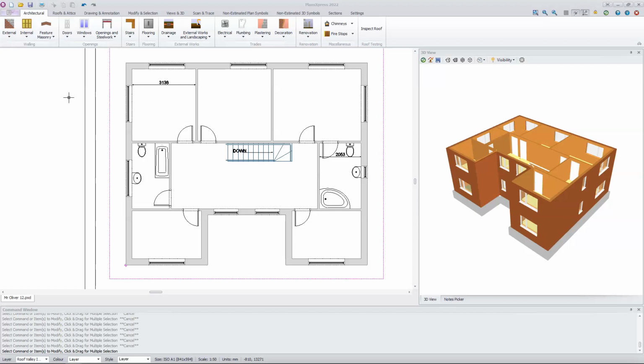I'm currently working in sketch mode to make the drawing page cleaner and easier to work with. Using sketch mode also helps the software run more quickly, as it doesn't have to keep redrawing the hatching. I'm going to start by placing some horizontal construction lines, which will help us place the roof and rainwater pipes.